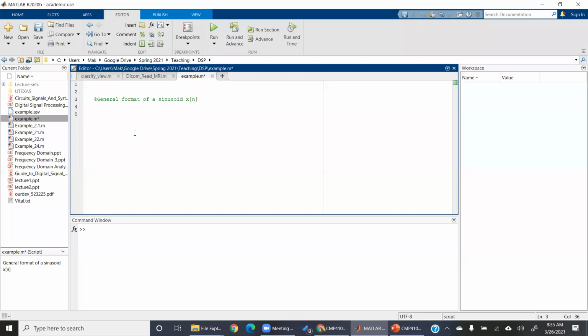You know the process involved in analog to digital conversion. You have an analog signal, and then you have a sampling frequency associated with the sampling time, and then you go through this signal and pick out discrete values, and you quantize those, and then you encode them into digital values. So when I write x[n], that's a discrete signal. If I write x(t), that's an analog signal.